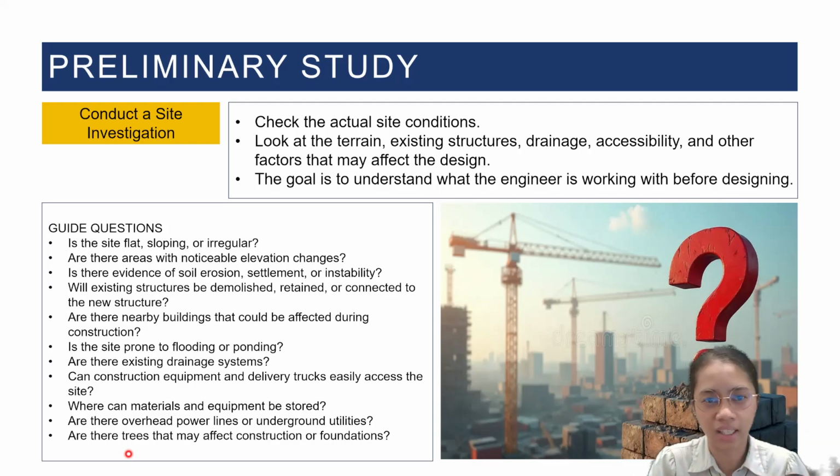If you will be retaining the trees, as a structural engineer you need to consider that the roots or the trees themselves will not affect the structure that you will be designing, because if the trees remain planted and continue to grow, they might definitely affect over time the structure that you will be building on that lot. On the other hand, if you will be pulling out the trees, you will need to apply for a permit to the DENR before you do the cutting of the trees.